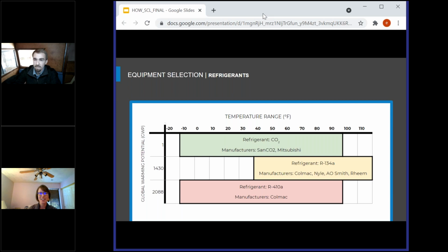And here's a question that we had yesterday, and I really think this is interesting. Can systems using high GWP refrigerants be converted to then use low GWP refrigerants at this time? And I'm wondering if that's possible because of this pressure issue with CO2. Yeah, so none of these conventional refrigerant systems could just be straight converted into CO2, for example, because the pressures are so special with CO2 and different things you need to consider.